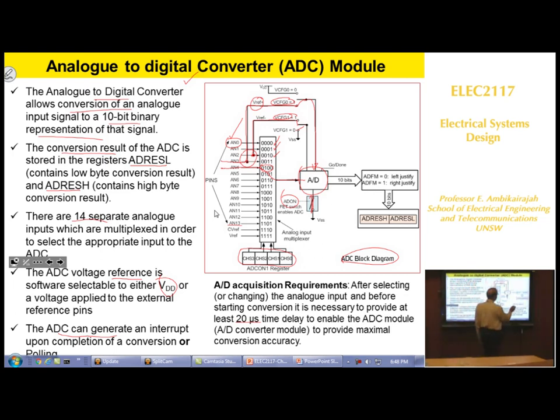So we're going to look at this A to D module. This is the simplest module where, once it's finished the conversion, 10 bits will be available, and this particular line will go low. That means the conversion is complete. To start the A to D converter, you first enable it, you connect this line, and then you set this bit to 1. When it's finished conversion, this GO/DONE bit will go low, and that means it's converted. And then you have 2 ways of reading the data, which I come to in the next page. The lower 8 bits will be here, and the remaining 2 bits will be here, providing the 10 bits. That is called right justification. If you go for left justification, you will have the first 8 bits there and the next 2 bits there. So you can have both ways.